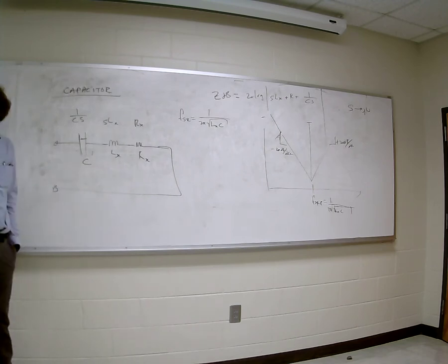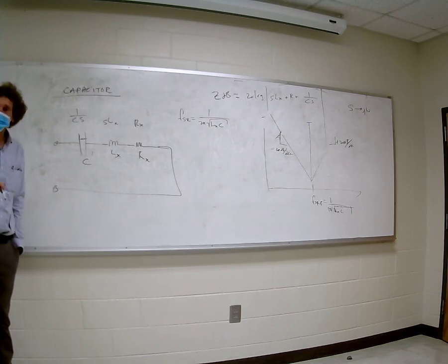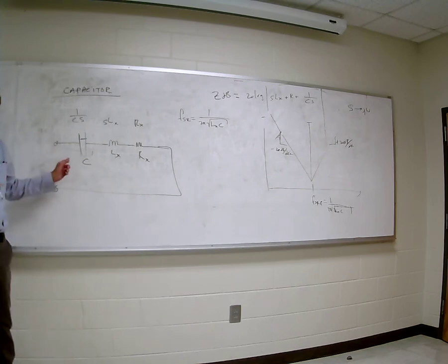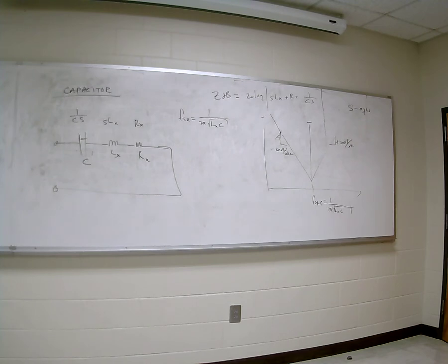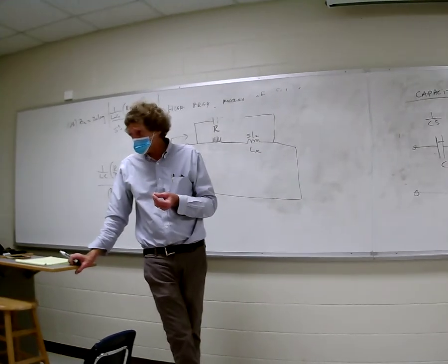Now, what happens at resonance? Do you remember one thing that happens at resonance always? I want to go back to this one. There's one overwhelming fact you should know as electrical and computer engineers. When you talk about resonance and you have an L and a C in a circuit, LCR circuits, the capacitive reactance is identical to the inductive reactance. Do y'all hear me? Except the sign is opposite.